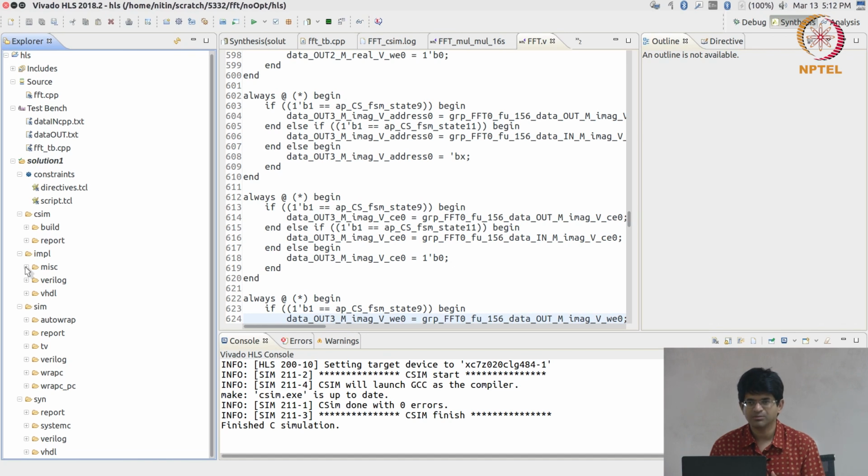So there are multiple ways of doing this kind of equivalence checking. There is one method called formal equivalence checking, which essentially says there are formal methods by which you can literally say you have the C code, these are the set of transformations that were employed by the compiler in order to convert that into Verilog, and by going through that process you can literally say that this line of Verilog corresponds to this input line of C, and therefore they are exactly functionally equivalent. Whatever the C code does is exactly what the Verilog code will do. In general, that is very hard to implement. We do not have such formal equivalence checking implemented over here.